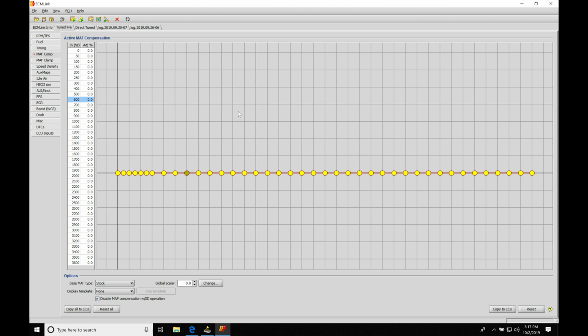It's going to compare the reading from the O2 sensor to the target air fuel we want to run at. In this case, it would be 14.7 to 1 or stoichiometric. So in the situation where we're going to have a difference, the short-term fuel trim would make the instantaneous or first correction. So whether we're at idle or part throttle, the short-term trim is going to always be moving around. You'll find we can log it and take a look. We actually have a data log here. We're going to be reviewing that here in just a second.